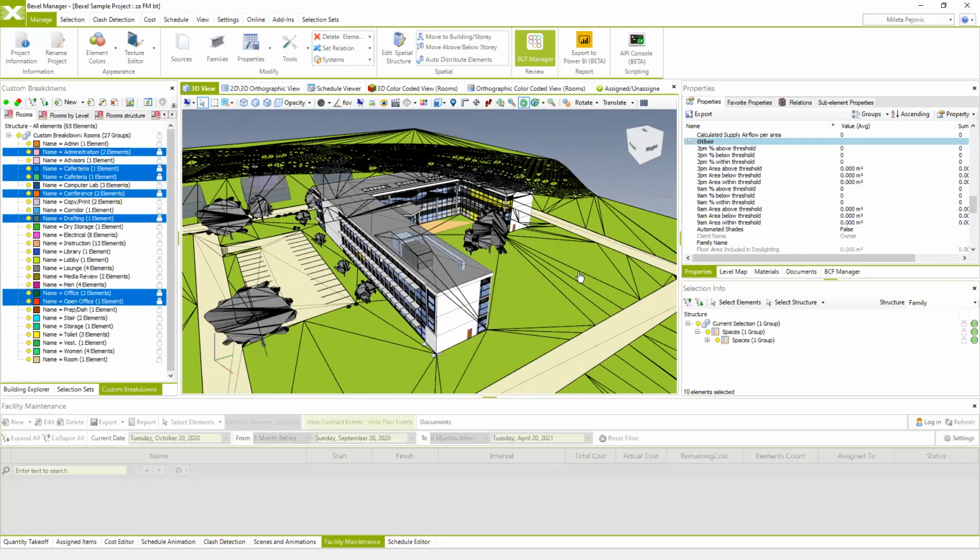So once you confirm that everything is according to the as-built project on site, the next step is to add specific information to your BIM model, which could be valuable and used for next processes, such as facility maintenance information, asset information regarding, let's say, installed equipment, warranties, all the necessary approvals and documentation which could be saved along with the as-built documents.